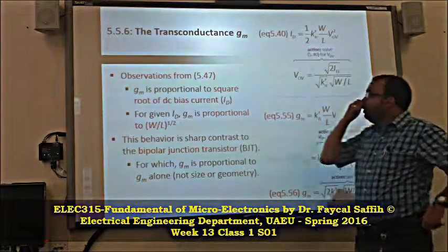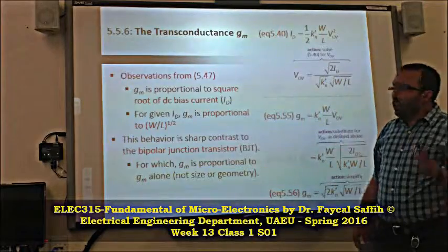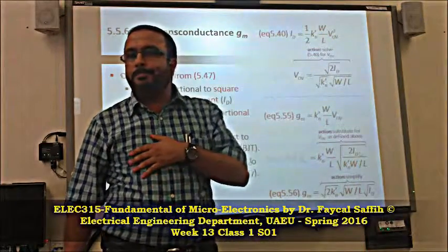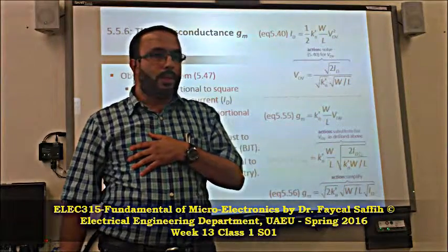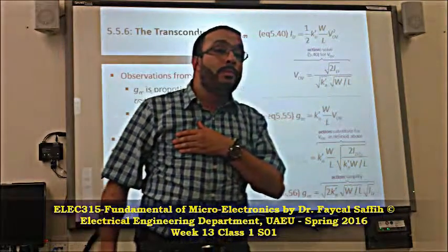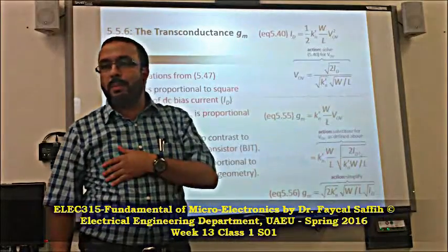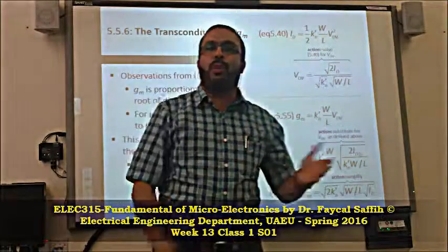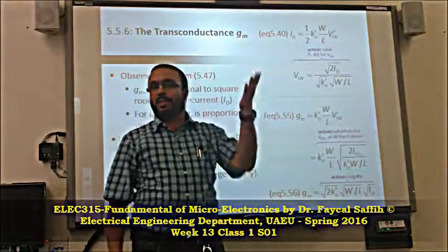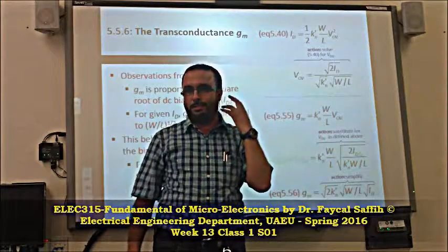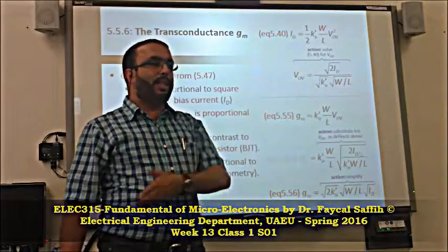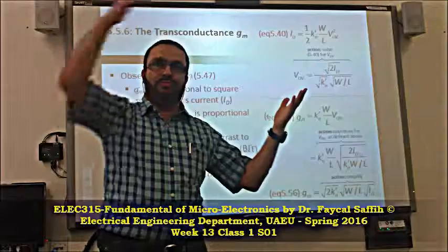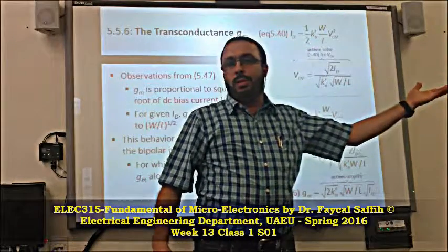Basically, we finished last time talking about the transconductance gm. What's the unit of gm? 1 over ohm. What does it remind you about 1 over ohm? Conductivity. Very good. That's why we call it transconductance. So it is a conductance unit, and trans is just because it's a transit thing: the input voltage turns into current in the output.